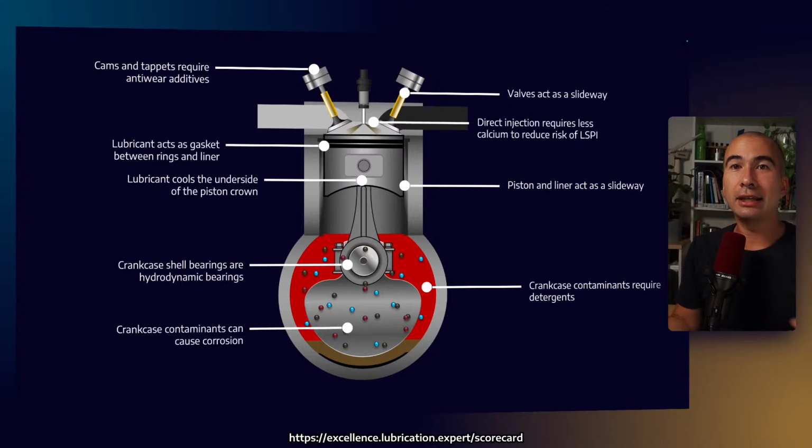So that's why we need things like anti-wear additives to protect the cams and the tappets, because the viscosity is not optimized for them. They have heavier loads and therefore we're going to see some metal-to-metal wear. And that's why an additive like ZDDP is important in engine oils. Now, I am actually working with a company that's working on an alternative to ZDDP. Have a look at the YouTube channel for a couple of those videos as we go through development of that.